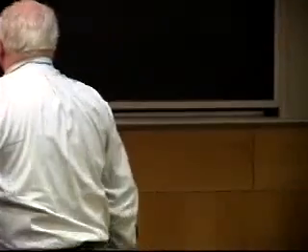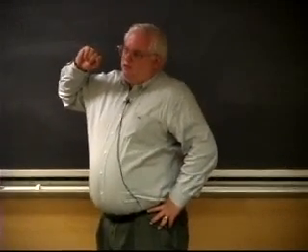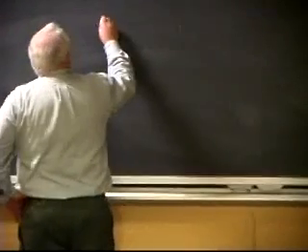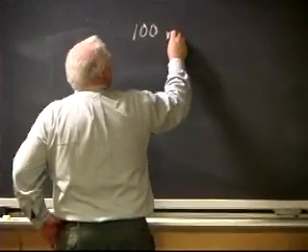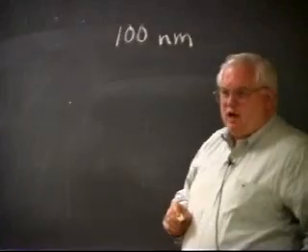Anyway, you can store lots of charge on high surface area, but you need a very, very high breakdown, something that will not allow the current to jump across it. Because let's think about it. If I've got an oxide layer that's 100 nanometers, and I want to put 1,000 volts across that.